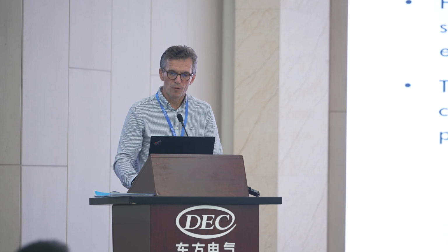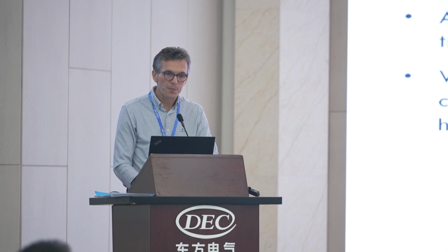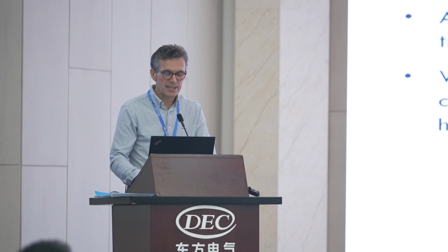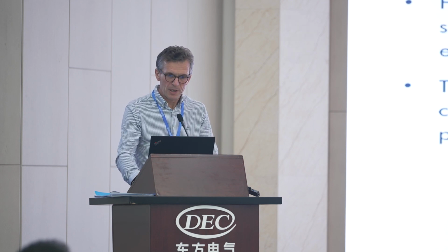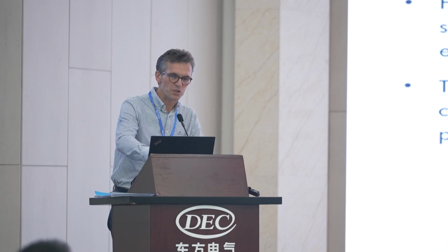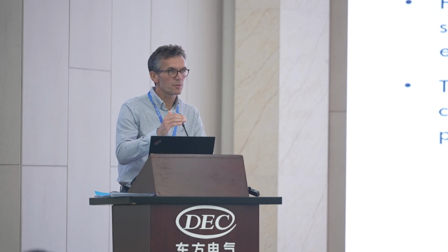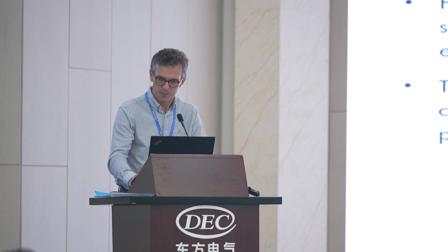This is an example of screening in the fluidized bed unit with the ilmenites T1 and T2. As I said, we originally discarded the T2, but as I forgot to say here, when this test was done for the perovskite, we observed some sulfur adsorption on the surface, and this deactivated the material. So we decided not to go further with this material for the pet coke case.